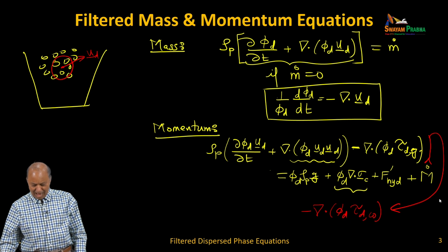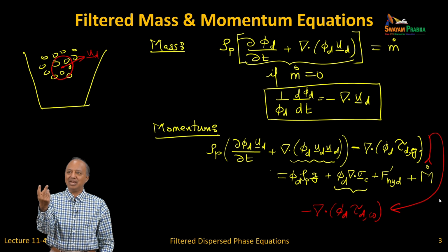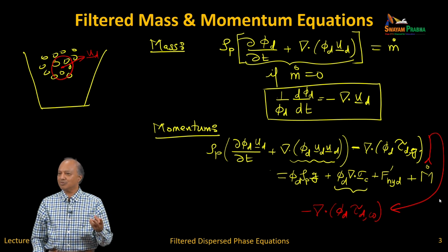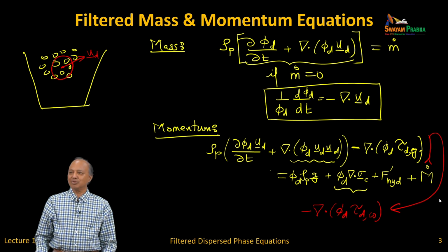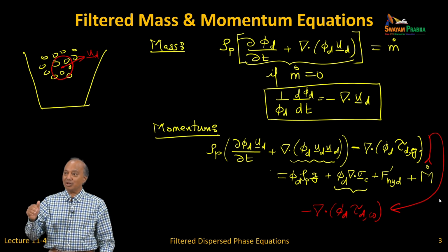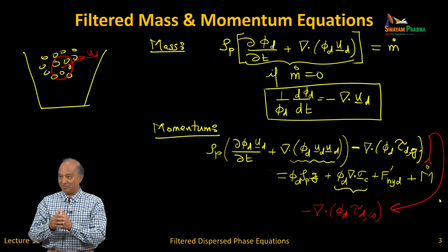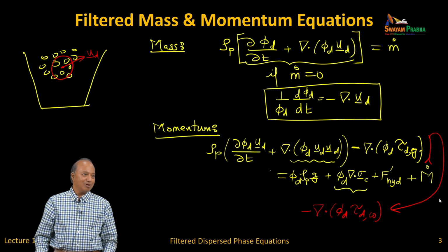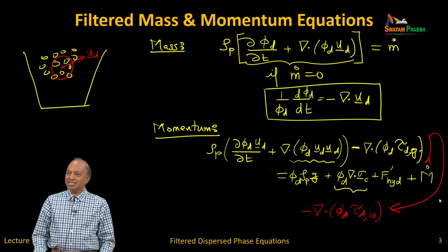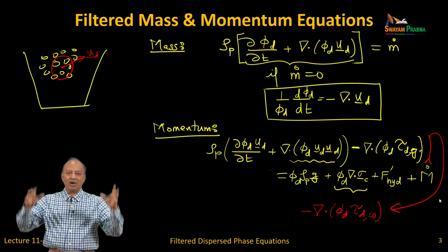So the same averaging, swapping the integral with the derivative, Gauss rule, Leibniz rule. The Gauss rule and Leibniz rule are very important because that's the only way you're going to get how particles and the fluid exchange mass and momentum. Okay, the Gauss rule and Leibniz rule are very important. This is one way of deriving. There are other ways of deriving in a finite volume context.